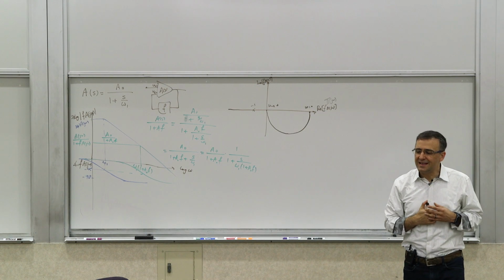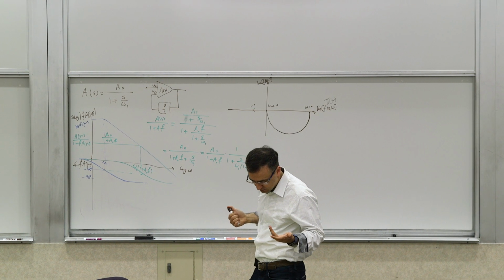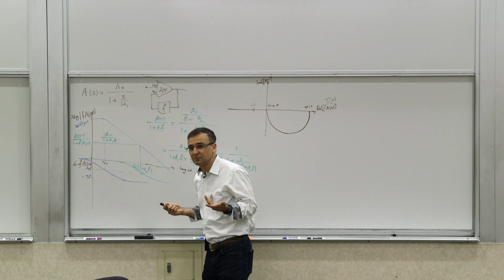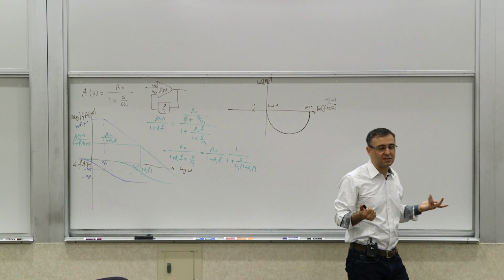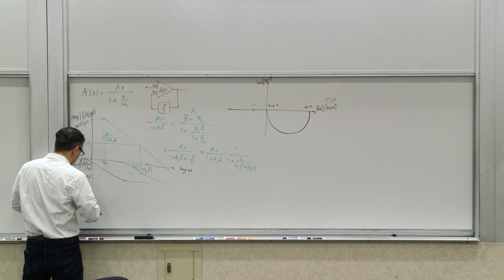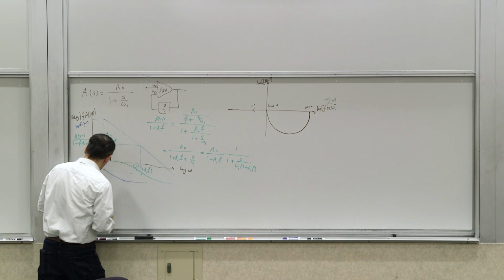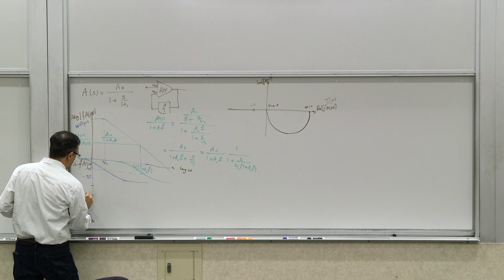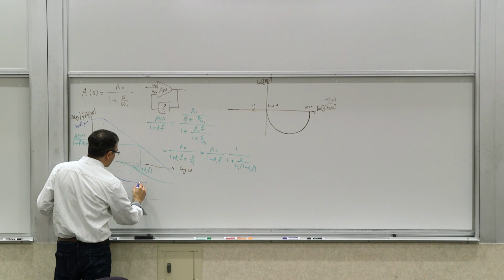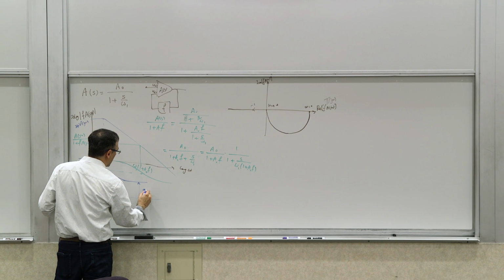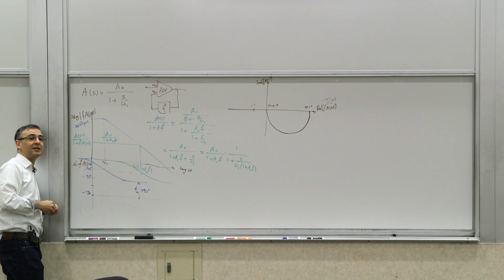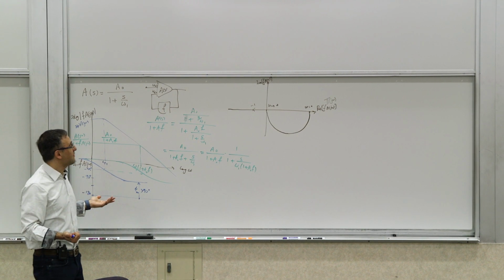Right? So from a linear standpoint, is this stable or unstable? This is completely stable, right? Now you can see that also if you want to think about the phase margin or things of that sort that we introduced last time. So basically this is negative 180. So no matter what you do, you have at least a phase margin of 90 degrees. So your phase margin is greater than 90 degrees. So the system appears very stable.